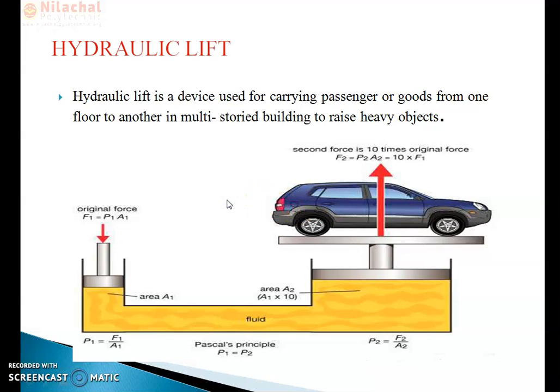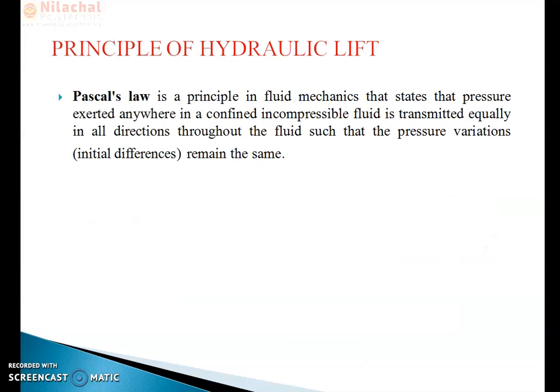Then you come to the principle of the hydraulic lift. This hydraulic lift is based upon Pascal's law. What is Pascal's law? It is the principle in fluid mechanics which states that the pressure exerted anywhere in a confined incompressible fluid is transmitted equally in all directions throughout the fluid such that the pressure variation remains the same.